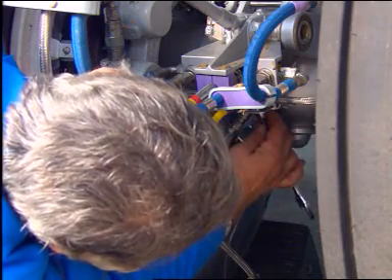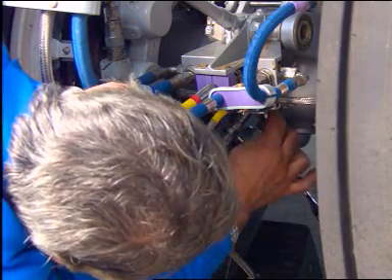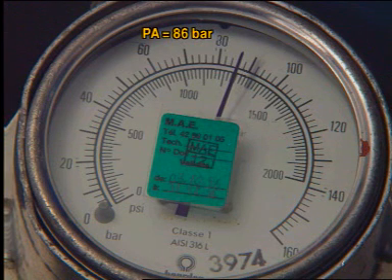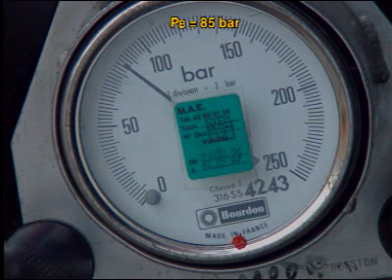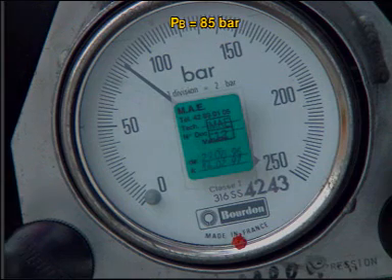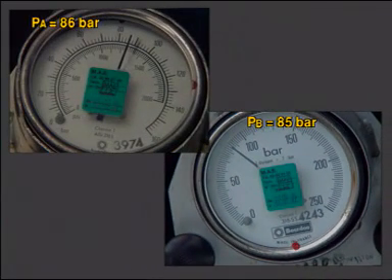Close the bottom charging valve. After 5 minutes, check the pressures. Open the top charging valve, read and write down the pressure, and then close it. Open the bottom charging valve, read and write down the pressure, and close it. Make sure that the pressure at the top and bottom charging valves are the same, plus or minus 1.5 bar. If not, you have to do the procedure again, starting from the step where the floating piston must be moved to the top of the bottom chamber.